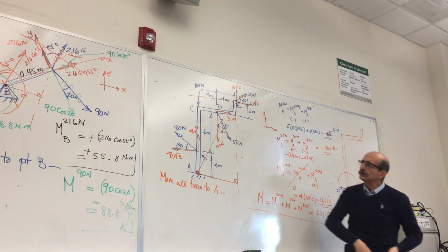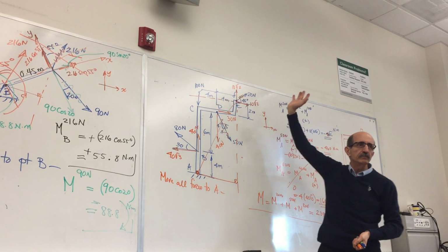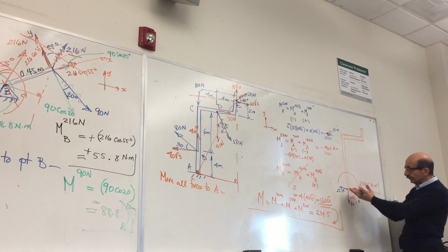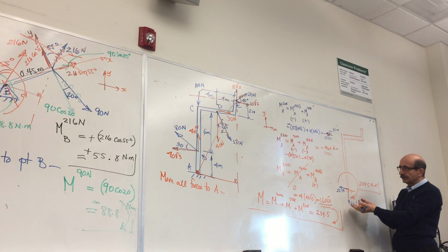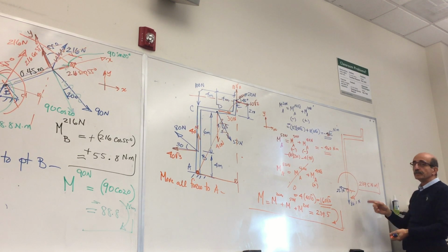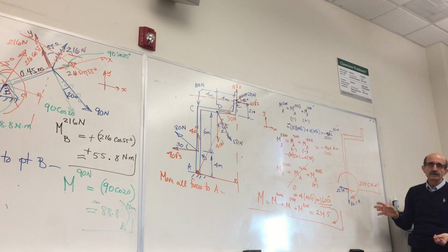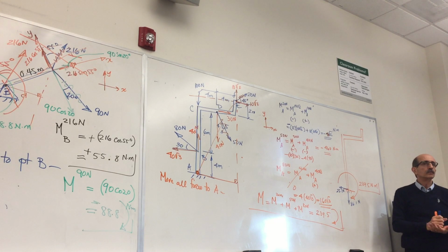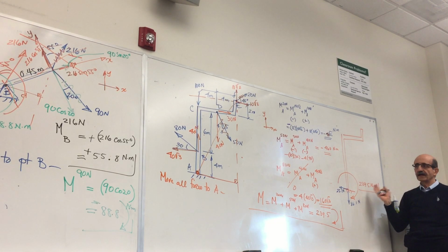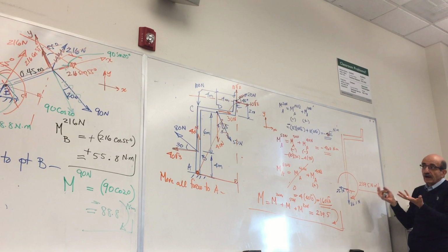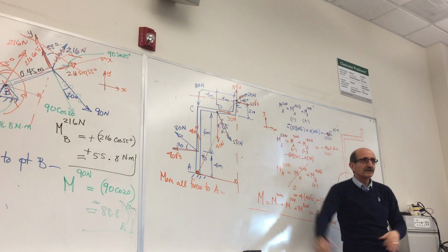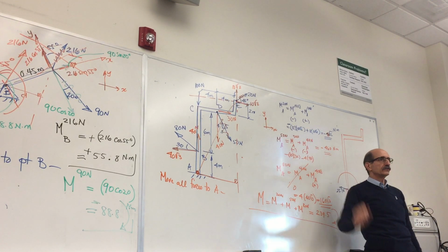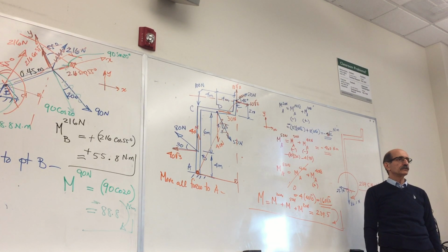So you can replace all those cables by just putting a single force consisting of these two components here, and adding a moment, or a rotational spring, that would exert a 239.5 Newton meter moment. As you can see, you have simplified the configuration of all these forces, but these two are exactly the same thing. Any questions?